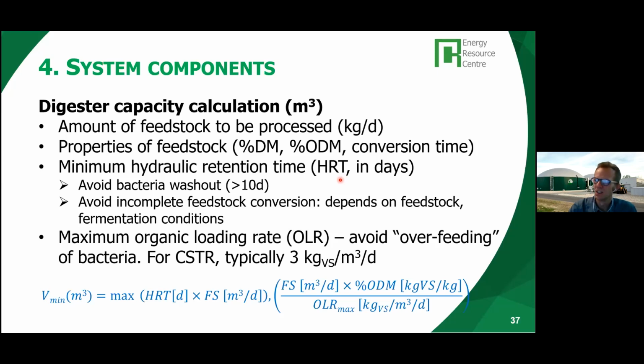Then there's not just the time required for the conversion of the feedstock, but you also have a minimum time that the feedstock needs to be in the digester in order to avoid the so-called washout of bacteria.